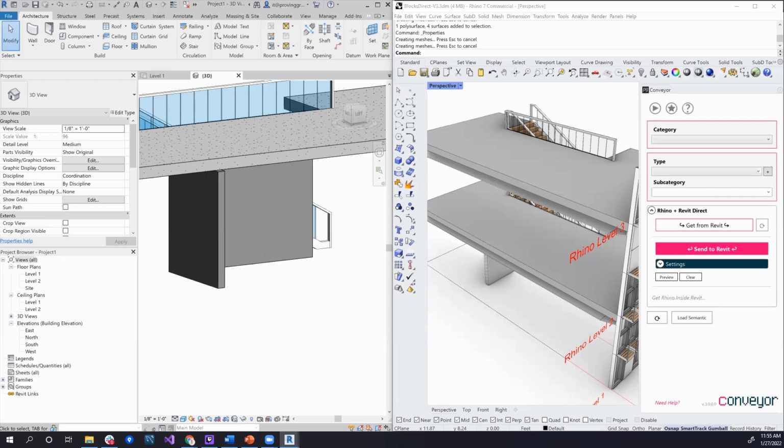So what it does is it's actually mapping material names to each other. If you have a glass material inside of Rhino, it's going to look for a material that is equivalently named inside of the Revit environment and assign that material. So it's not creating or recreating the materials. That could get pretty messy, especially if you have your own material library. But we're allowing the user to map between material names and find matches in that manner.